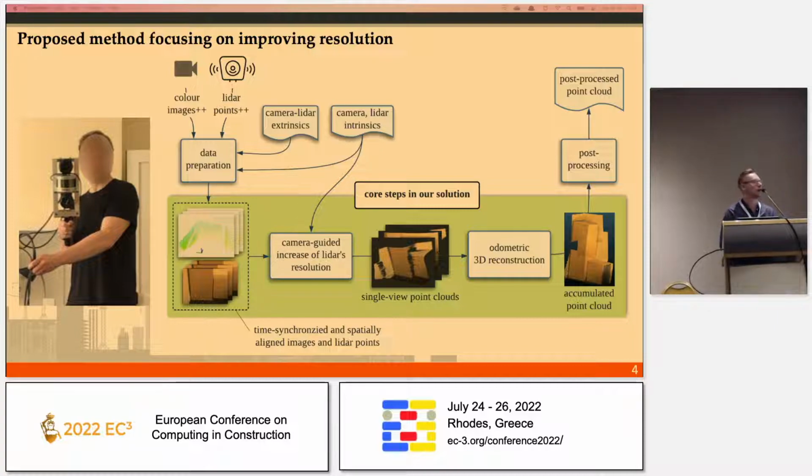This is done offline through something called camera-LiDAR extrinsic calibration, where the point is to estimate the rigid body transformation between the coordinate system of the camera and the coordinate system of the LiDAR. Once I have this transformation, I can, for example, project LiDAR points onto the camera space, and vice versa, I can project pixels onto points of the LiDAR, and this is basically how colorizing of point clouds happens.